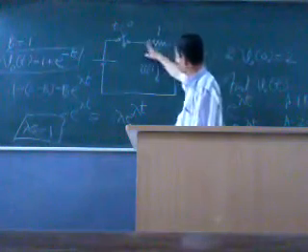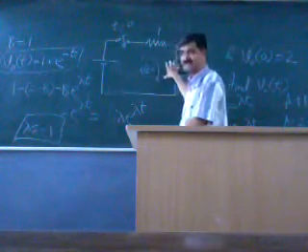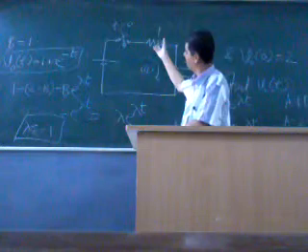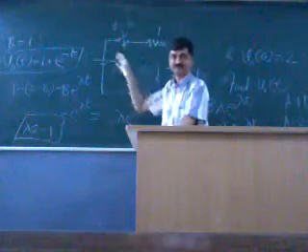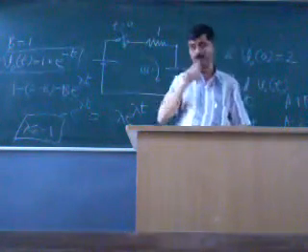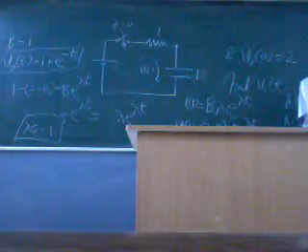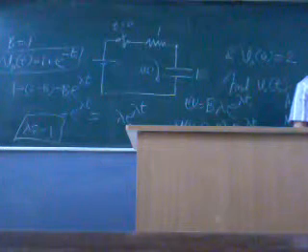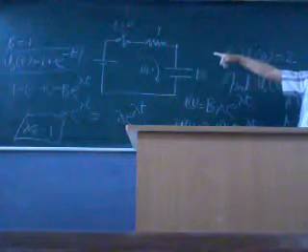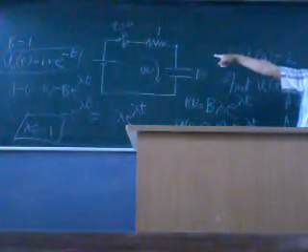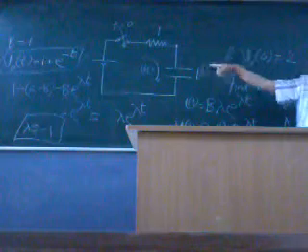this voltage, you will find this current, you will find that at every point of time both of these match. Because of this current there will be some voltage across this, and you will find that this voltage always matches with this. Once we solve by this method also, we find the voltage across the capacitor, we find the voltage across the resistor, and then we see that both of them add up to always 1. So voltage across the resistor in this case would be e raised to minus t, because minus e raised to minus t.